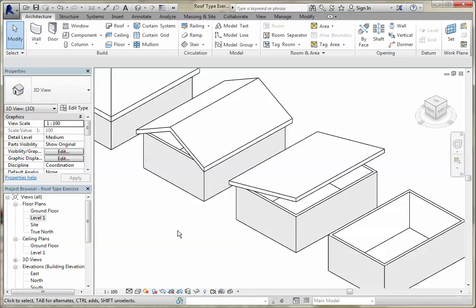Now some houses have almost flat roofs. When you see the house, it doesn't look like it has a hip type roof or a gable type roof on it. Sometimes it just looks flat. Often they will be using bond deck type roofing, and they will have that down as low as 5 to 10 degrees. So you may wish to look at using that type. Others, more architecturally designed type houses, will often sometimes use a combination of different angles at slopes to give it a nice look, a mountainous sort of look about it.